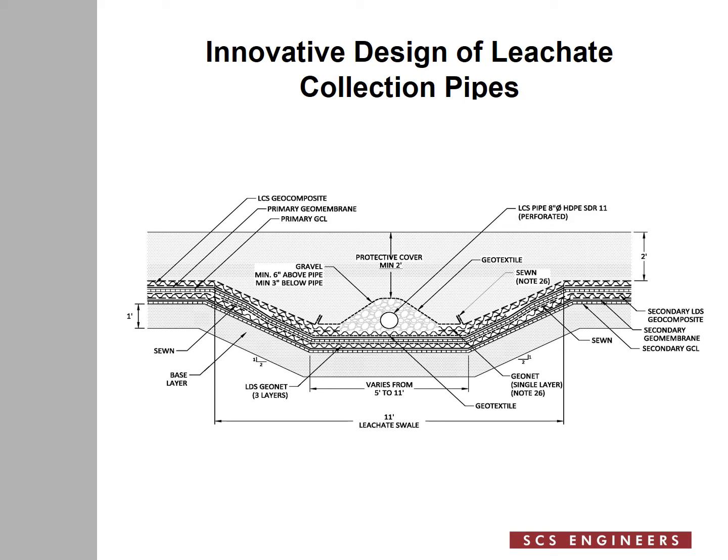Now, if you envision the flow of leachate from the base area in the composite coming to the trench, you will notice that the liquid in the geocomposite goes directly from the geonet into the gravel, which in a sense meets the rule of transmissivities.